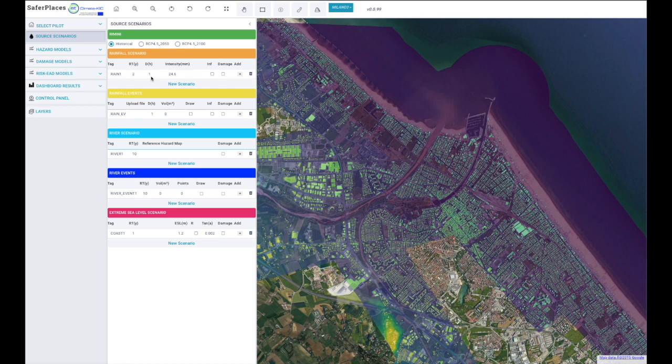With the orange panel the user can set up a tailored and specific rainfall event characterized, for example, by a specific rainfall intensity in millimeters and duration in hours. With this option, the rainfall intensity is considered uniform for the entire study area. The checkbox inf is related to the possibility of activating the natural green infiltration model.